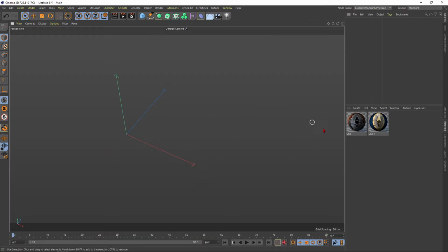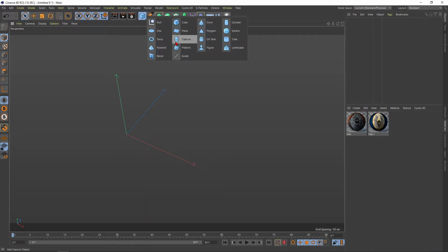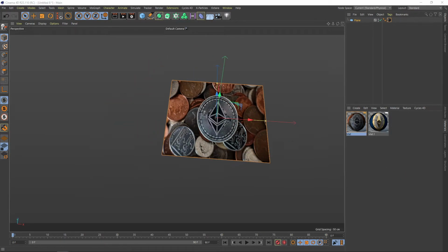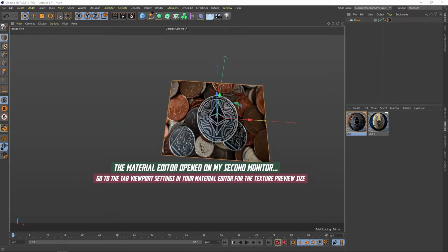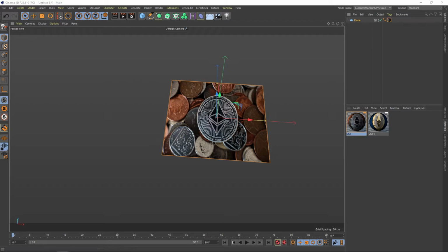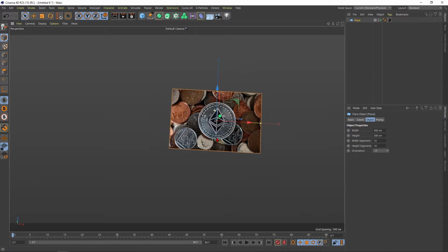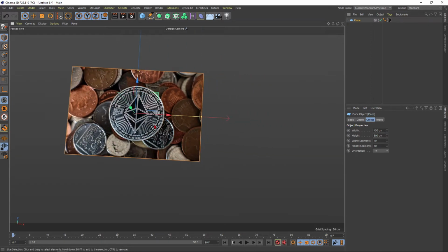Alright, welcome to Cinema 4D, and you can see I already downloaded 2 images as reference. So let's just select a plane here, put one of these ones on it. I guess in your case, the viewport resolution will be set to default, so it looks quite muddy, but just pump it up a little bit and then you have something like that. Just check the resolution here. So this is 4500 by 3000. So click on your plane, put this one, for example, to just a tenth of it. And now this is like the correct aspect ratio.